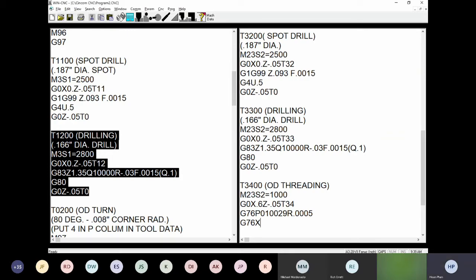So the finish diameter is going to be 254 610, something like that. Okay, and the Z dimension, we want to go a little bit past over the thread, but we don't want to go into a shoulder. So we want to say, okay, 390.